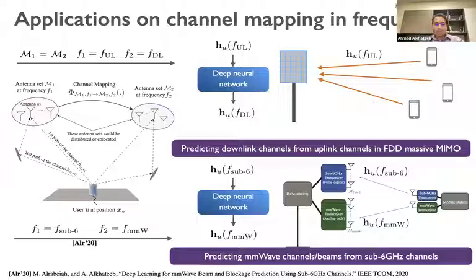Bypassing channel estimation. Yeah, as I was replying to the other question, on the channel estimation, in my opinion it is different from beam prediction. Beam prediction, I could probably think of as more like a statistical metric. It's a zone or a cone, where you don't need to be very accurate in beam prediction. But the channel is something, the complex channel vector or matrix, that needs to be acquired very, very accurately. So I think using machine learning to directly eliminate the channel acquisition problem may not be very practical, at least in my opinion.